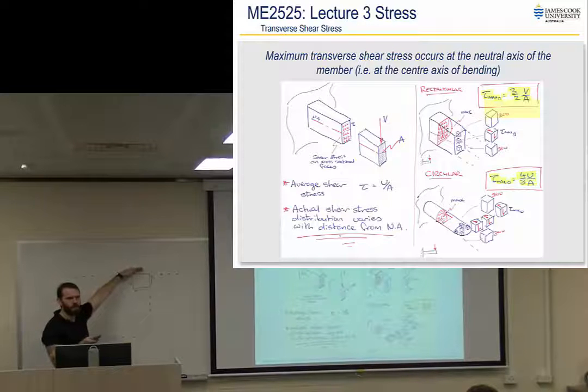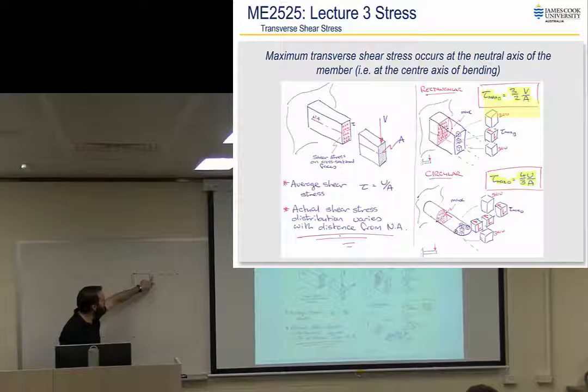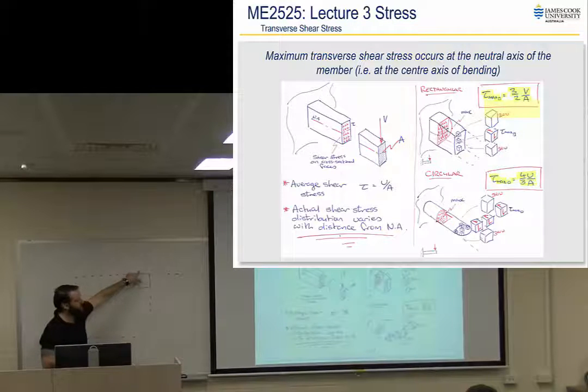And what we know about shear is that whatever the shear on this face is, this face has to have exactly the same value. And this face, and this face. So we know that for transverse shear, because it goes around in a circle like this, because it's in plane, at the very top edge, that stress has to be 0. Same story at the very bottom edge.